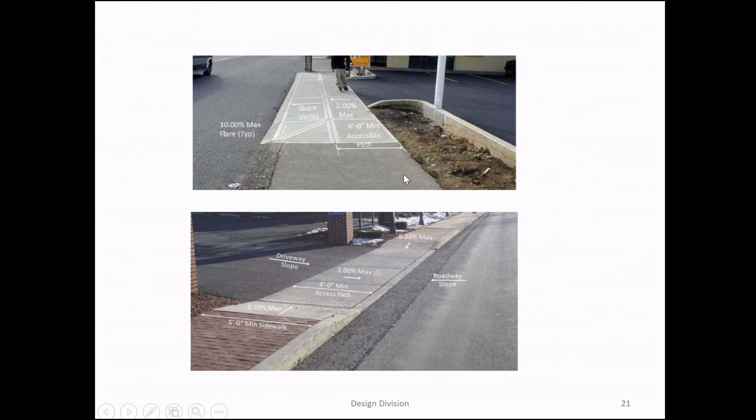You have to adjust gates, and if it's a swing gate, it's no problem, but if it's on rails, it gets a little bit more complicated because you might have to reconstruct more concrete or more surface if the rail extends past this point. Let's say the gate slides this way, and you're depressing it, you have to depress this, and yeah, be careful. Also, a swing gate is a problem too.